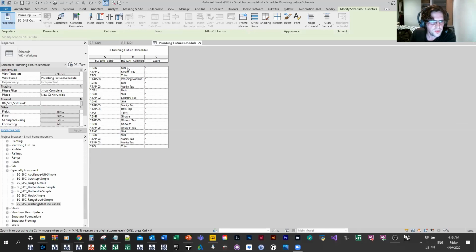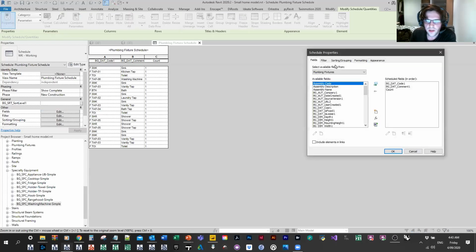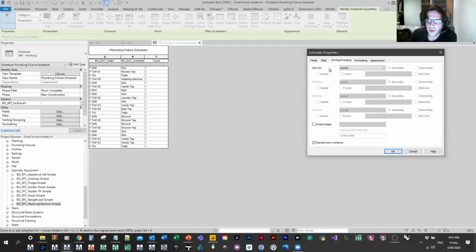So at this point, we get an itemized schedule. So every row represents an item. So at the moment, everything's just one of something. So it's not a very useful quantity takeoff at this point. Typically, you may want to filter as well, but in this case, my system is quite clean, so I don't need to filter. But I'll do some filtering later on.